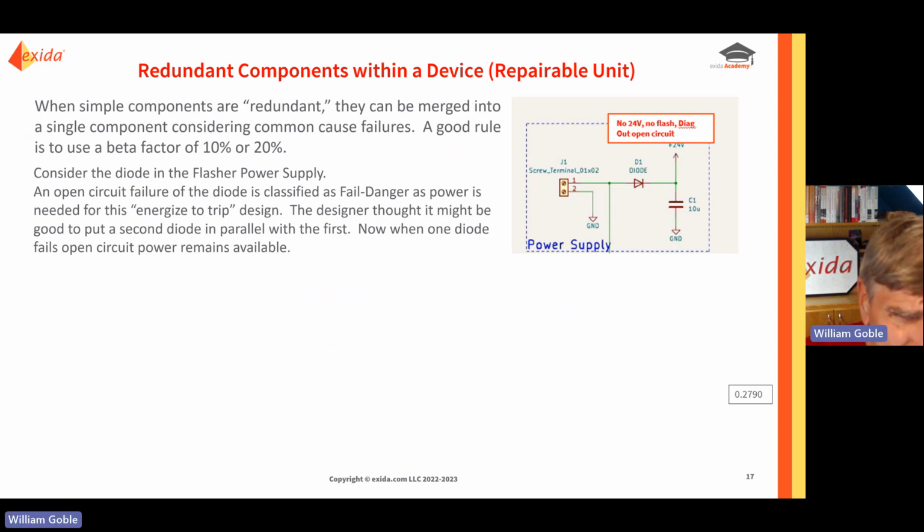That's fail danger. And so the designer focused on this particular component at the time, thought, wow, we're just going to put in a second diode. Then, even if one diode goes open circuit, the other will still supply the power. Isn't that a wonderful design change?